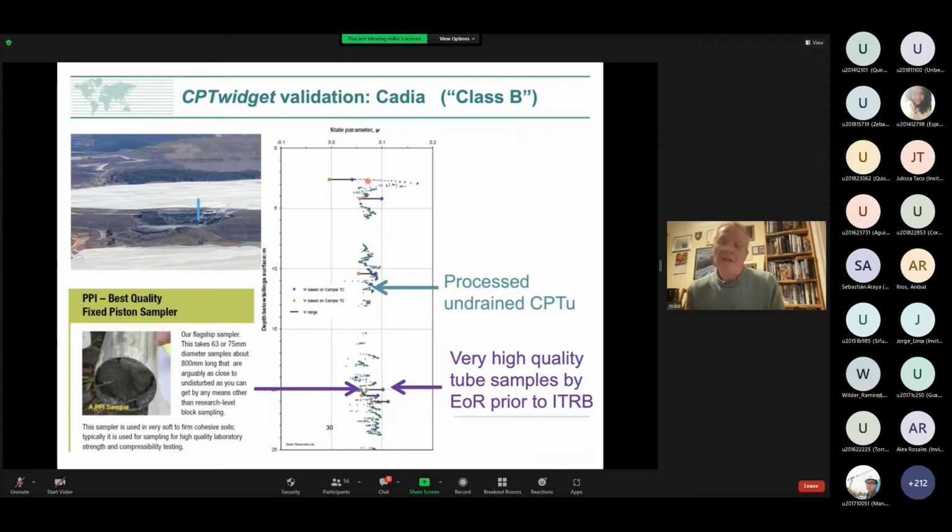Now, these tailings were a little bit stratified, so we were not entirely sure what was in the tube. But broadly, there was a predominant silty tailings and a slightly sandier one. So we actually determined the CSL for the predominant tailings, which is the purple dot, and for the sandier tailings, which is the orange dot. And truth has to lie between those 2 points. We didn't know whether the tube was full of sand or full of predominant material, but we said, okay, we'll just draw the band. And you can see we've got 6 of these, and it really beautifully straddles our prediction.